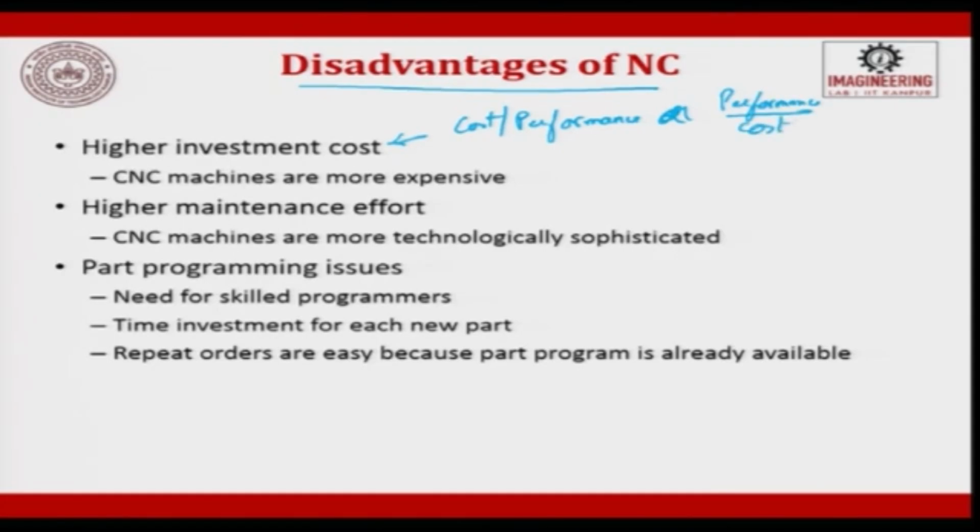So, a ratio has to be taken, and you should really work out if there are small parts to be made, and if the costing is extremely low, for example, less than 1 rupee or less than $1, then it is better to avoid NC machines, because you will never be able to come to the break even. So, that is what makes it expensive.